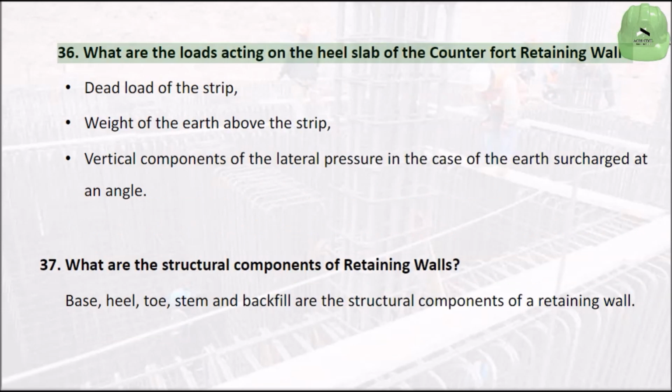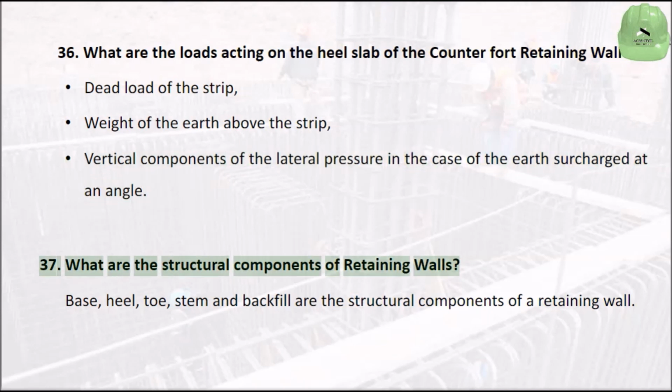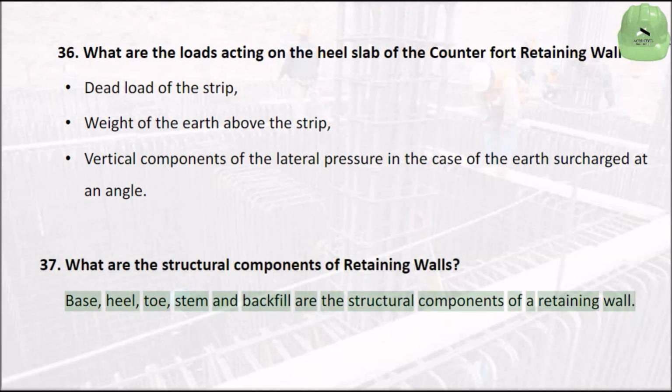What are the loads acting on the heel slab of the counterfort retaining wall? Dead load of the strip. Weight of the earth above the strip. Vertical components of the lateral pressure in the case of the earth surcharged at an angle. What are the structural components of retaining walls? Base, heel, toe, stem and backfill are the structural components of a retaining wall.